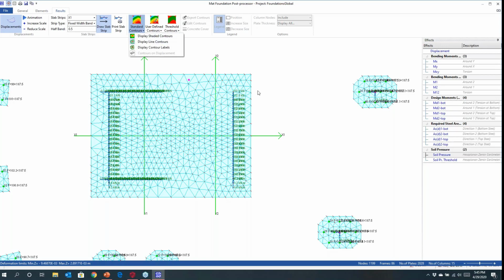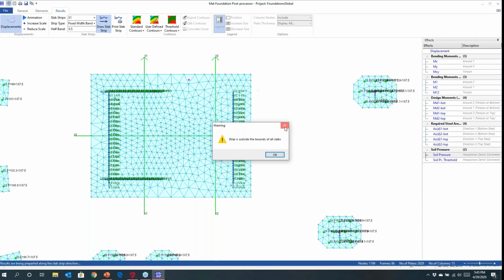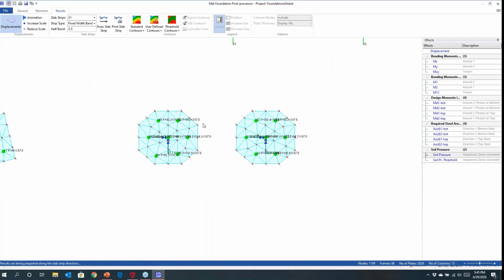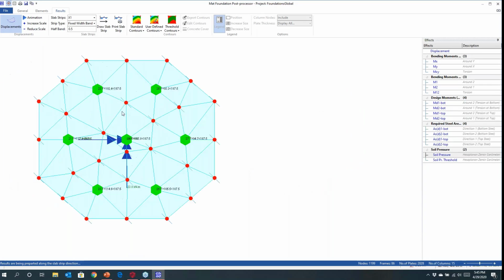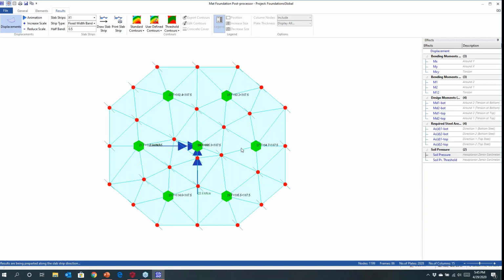Now, at the same time, what we're also doing is meshing other elements within the foundation. So you can see that we're meshing pile caps here, and we also provide you with the forces for the piles within these meshed elements. So you can see a range of forces within the pile cap arrangements here. Because we use rigid cap theory for the design of pile caps, and we're assuming cantilever theory, we don't take the finite element results.